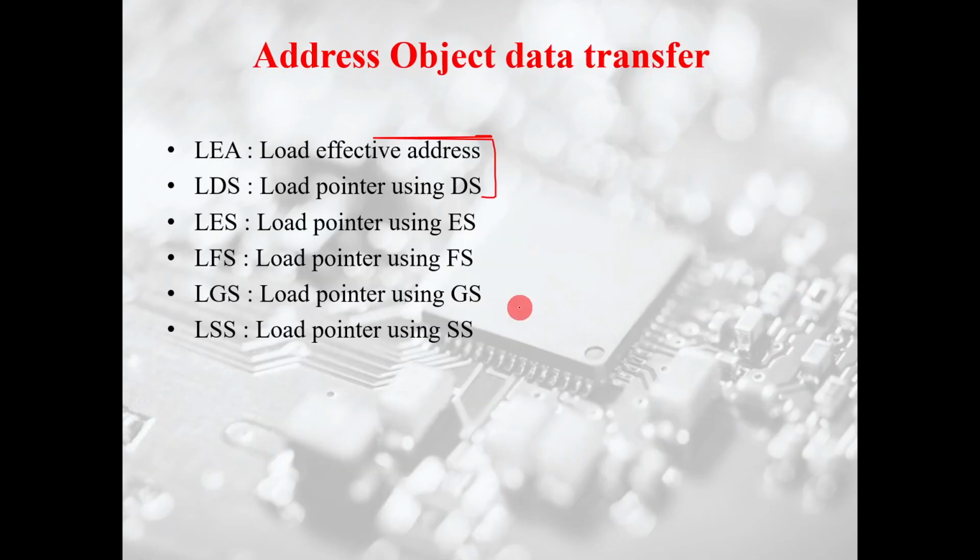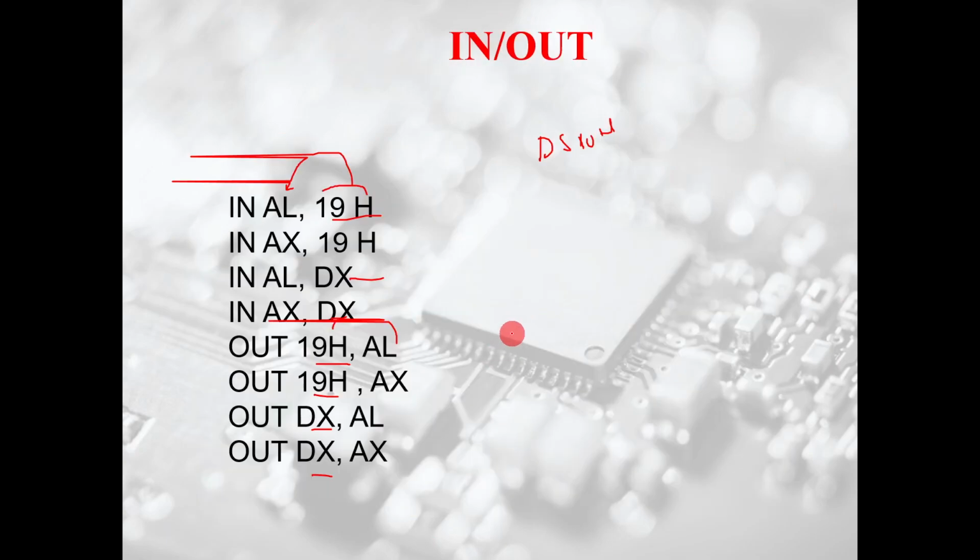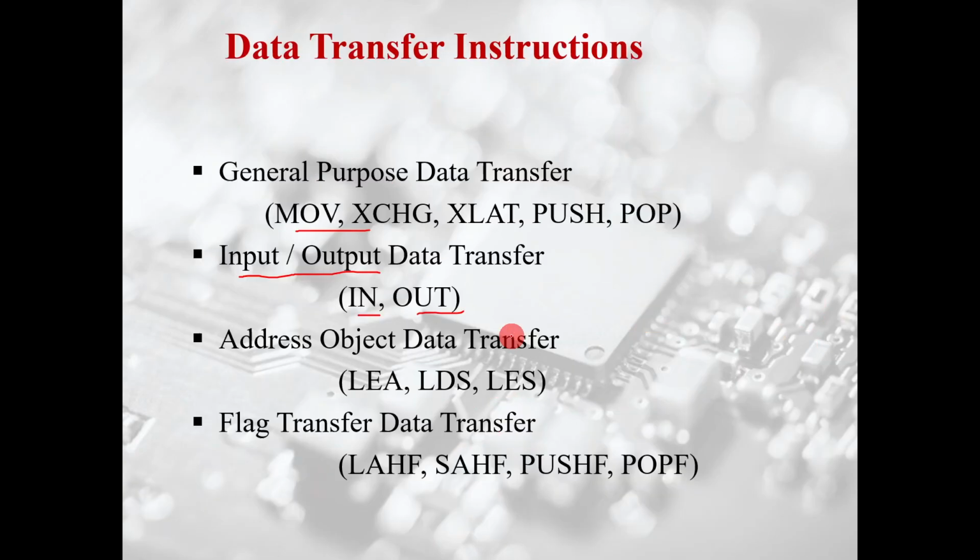In the next class, I think I missed out a few things. Let me go back here. Flag, PUSHF and POPF. I'll cover these two and then we'll do the rest. So just to give you a hint, PUSHF is going to put the contents of the flag register into the stack.